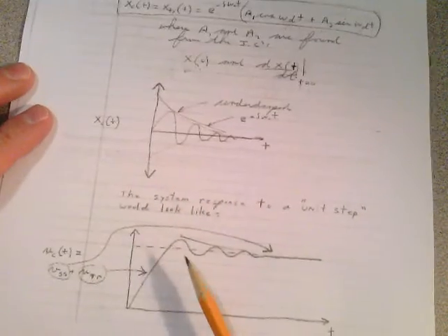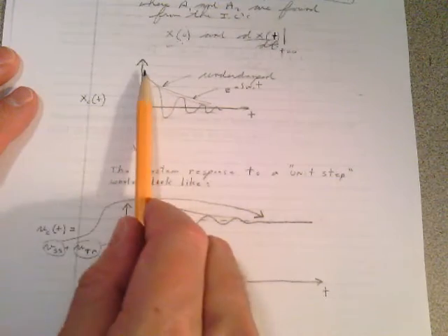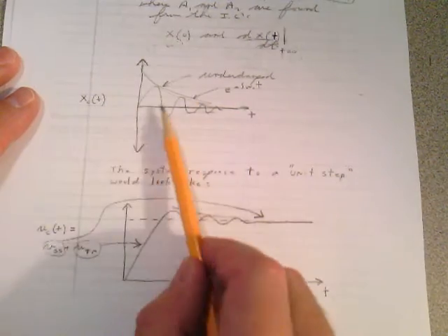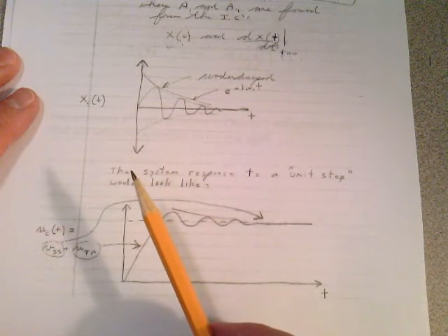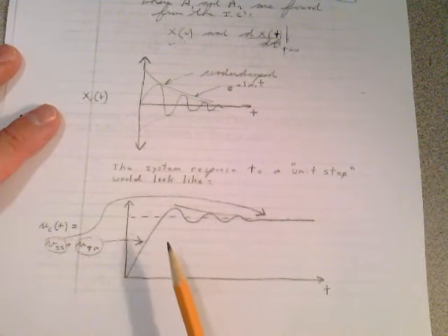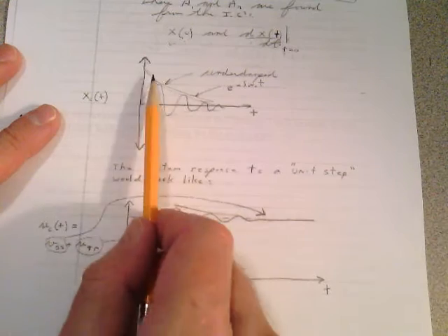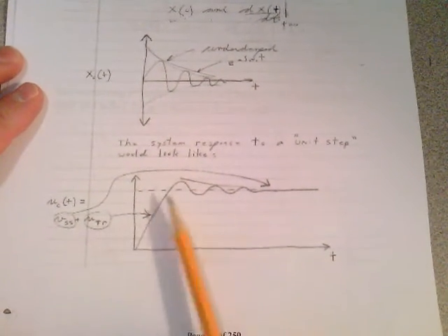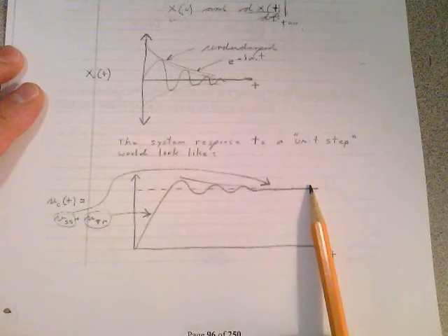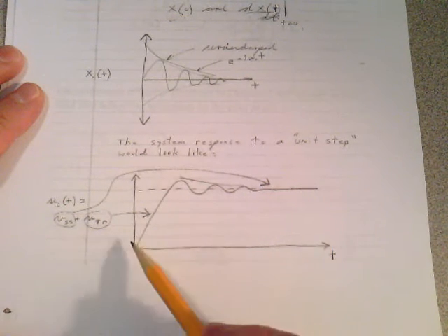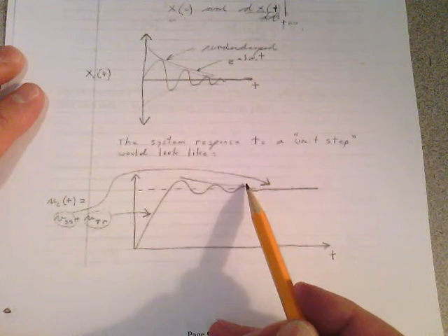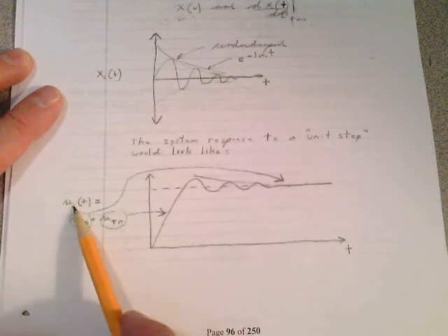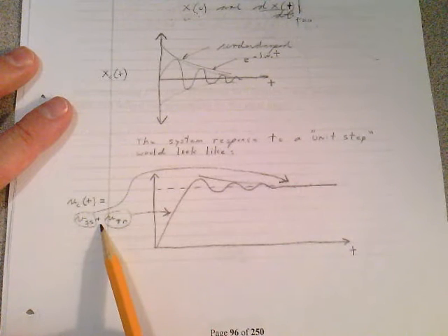I want you to notice that I'm showing you here a decaying exponential, what it looks like. It has ringing. You know why it's ringing, because you get a transfer of energy between the components. And the reason it's decaying is the resistor is eating up that energy. And down here, if you have a step response and you have a final value, I want you to notice that we have a transient here. There's our transient. That's what we're concerned about. Then we have a steady state solution. So the final solution turns out to have a steady state value plus a transient.